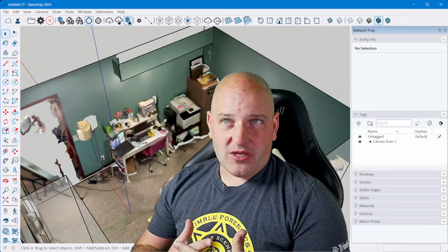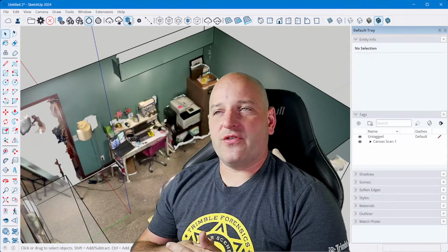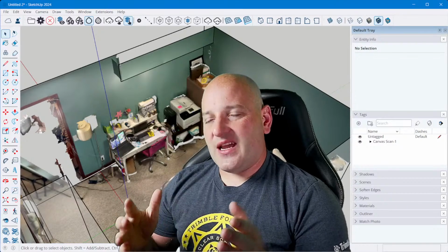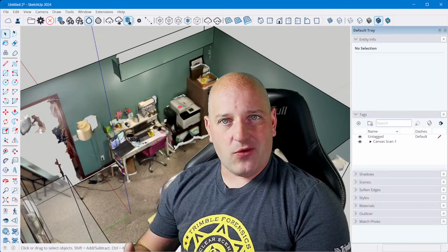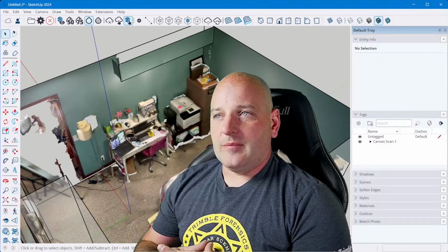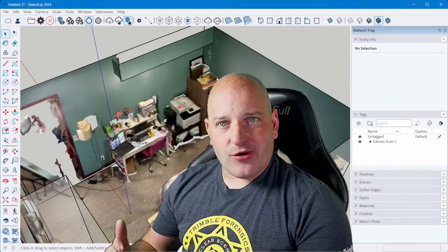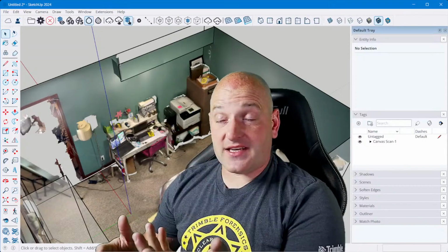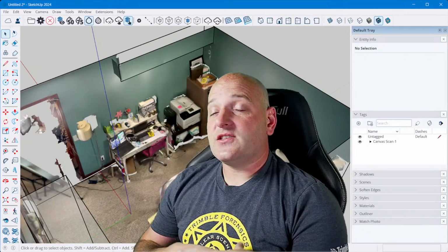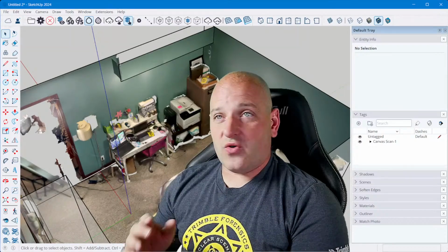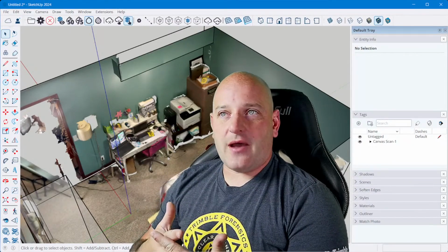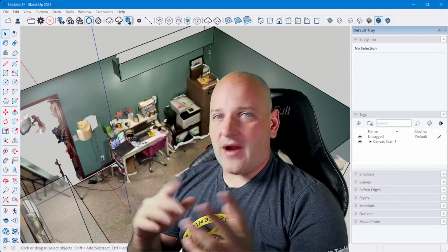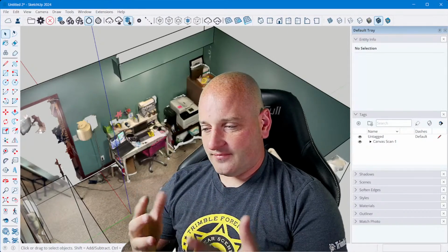Now, what I would normally do, if I was doing a lot of this over and over, is save my doors as my own model in my own model library, if you will. You can do that in SketchUp. You can have your own model library. So take these doors and create them with the 2D swing the way that you want them, so that you can just go grab them from your own model library.